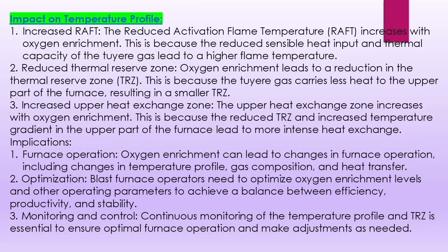Impact on temperature profile. 1. Increased RAFT. The raceway adiabatic flame temperature, RAFT, increases with oxygen enrichment. This is because the reduced sensible heat input and thermal capacity of the tuyere gas lead to a higher flame temperature. 2. Reduced thermal reserve zone.